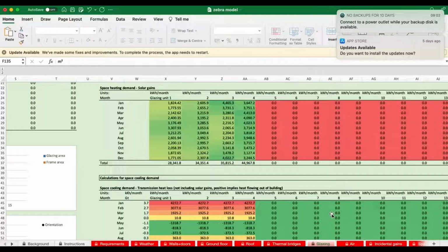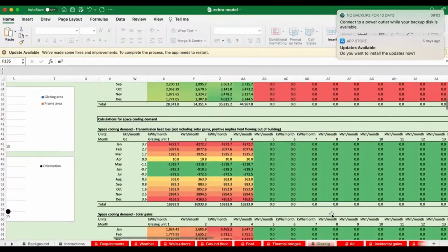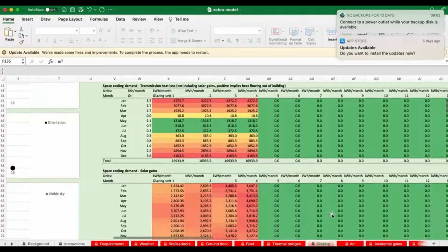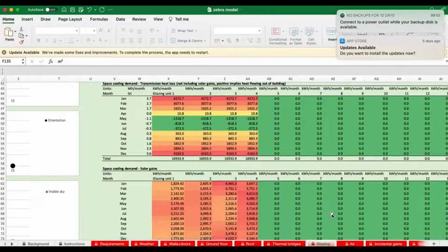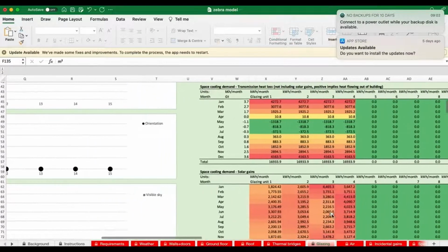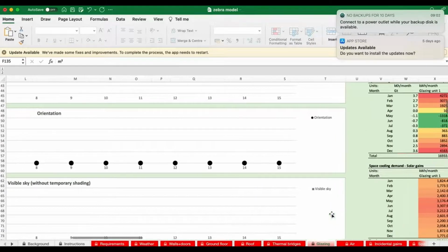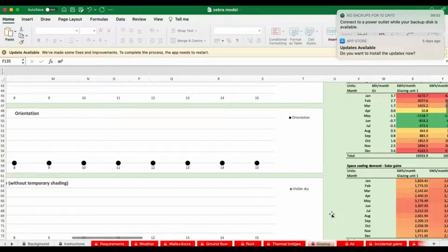think about the building differently on those different facades. And that's very common in architecture. If you're going to maximize energy saving, is to make sure that the components of the building that you use are chosen with respect to which way the building faces and how much shading it's got on different facades.